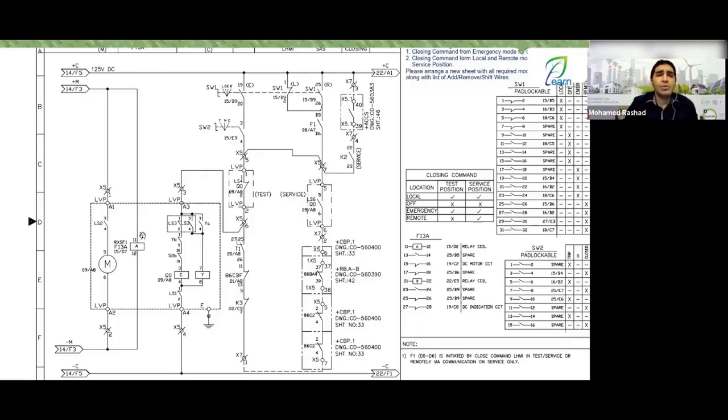So in the normal situation, when a supply comes to this circuit, this coil is always working, so it changes the position of its contacts. What will happen when the supply is cut off, for example, maybe a fuse has blown, maybe someone opened the link of the terminal block, maybe a wire got disconnected or cut, maybe there's any problem in the DC circuit, positive and negative?